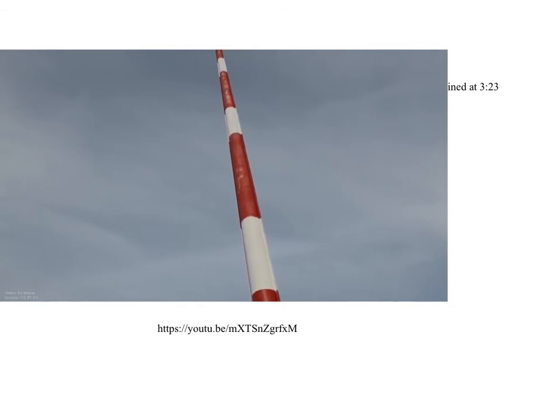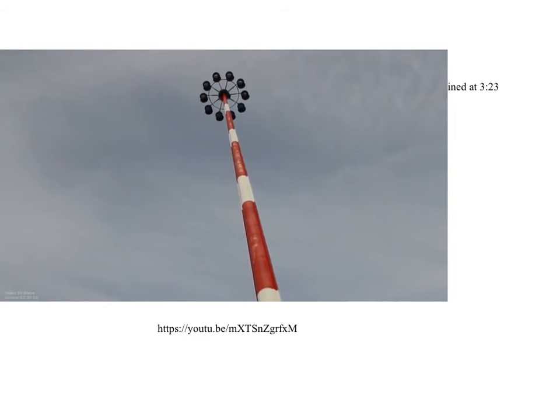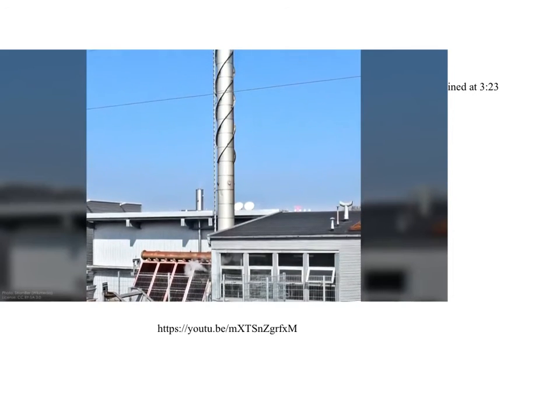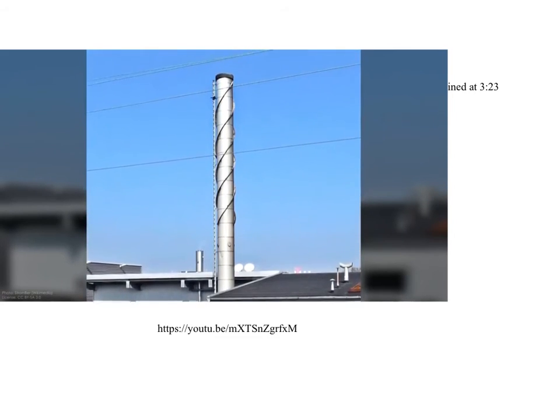In the case of wind-induced motion, the periodic driving force comes from an effect called vortex shedding. This is where fluid flowing past a blunt object oscillates as vortices are formed on the backside. When these alternating zones of low pressure occur at a frequency near the natural frequency of the structure, even small amounts of wind can lead to major oscillations. This is why some chimneys are equipped with helical vanes to create turbulence and break up the vortices.